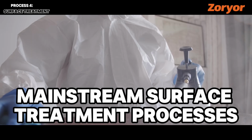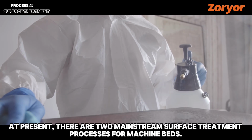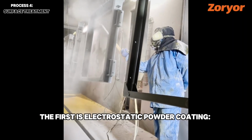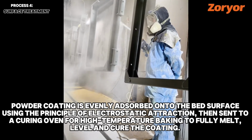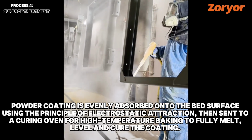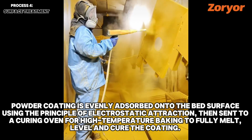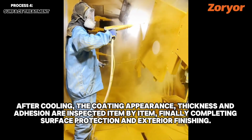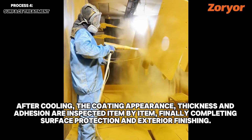Mainstream surface treatment processes. At present, there are two mainstream surface treatment processes for machine beds. The first is electrostatic powder coating. Powder coating is evenly adsorbed onto the bed surface using the principle of electrostatic attraction, then sent to a curing oven for high-temperature baking to fully melt, level, and cure the coating. After cooling, the coating appearance, thickness, and adhesion are inspected item by item, finally completing surface protection and exterior finishing.